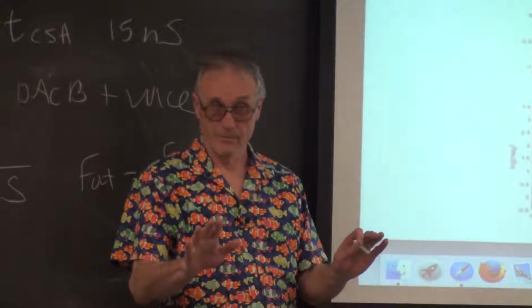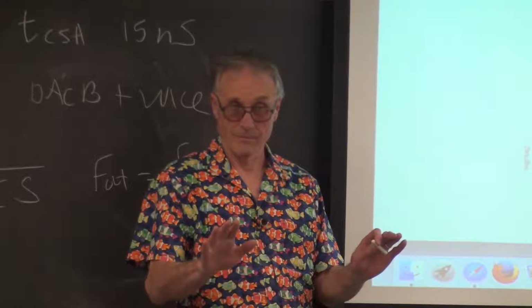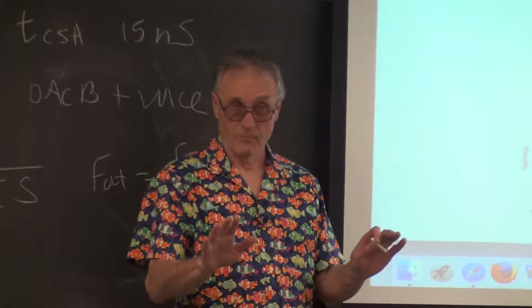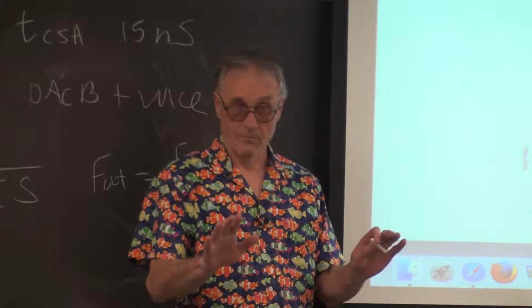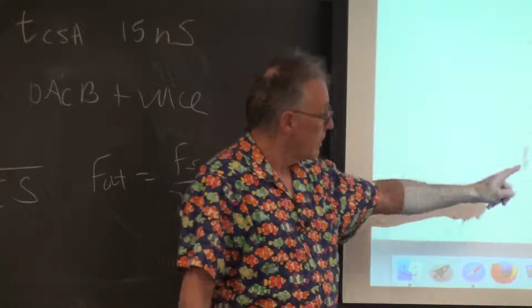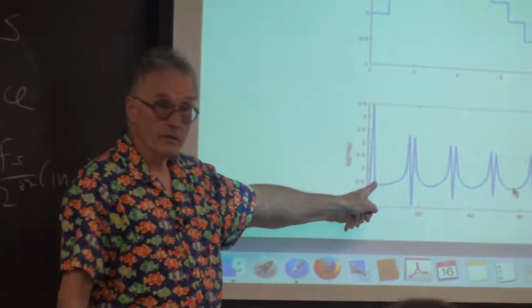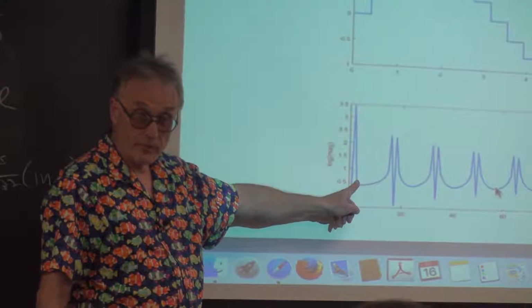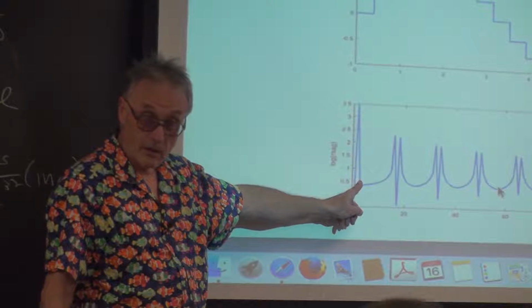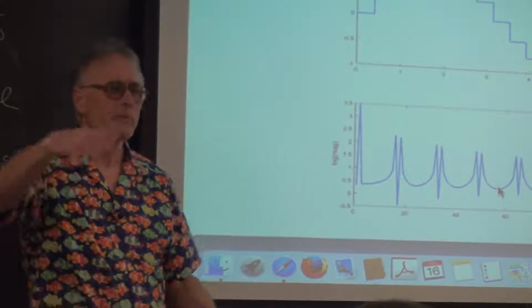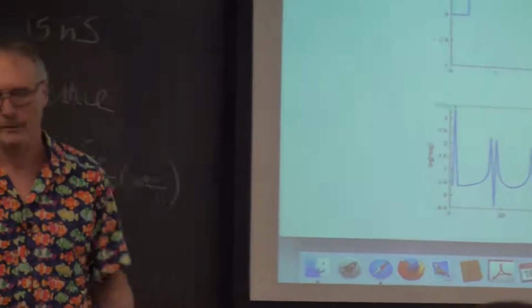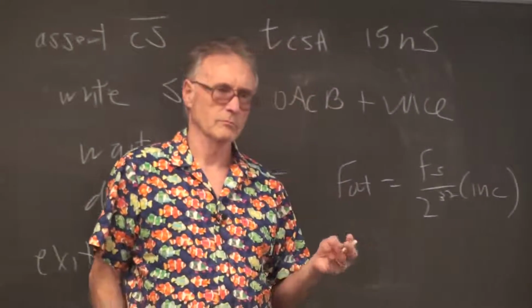The input signal also looks fine in terms of it's sinusoidal, but it doesn't read at like 1500 hertz, for example. Was this at 1500 hertz? You say looks fine. Was it at the right frequency in the FFT? No. Okay, so what I mean by looks fine is that the harmonics, the general structure looks right. Yeah, the structure is right, but the frequency reading is not.